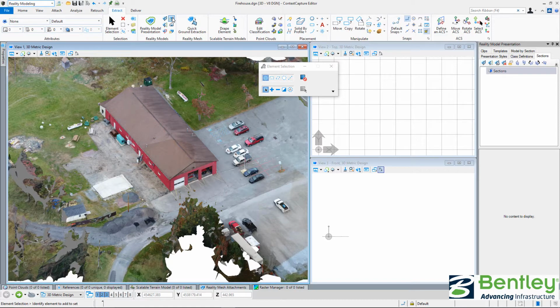So what I'm showing you here, if you have somebody going out and giving you LiDAR, you'll be able to create a surface from that LiDAR too. Many times if you're getting airborne LiDAR, depending on the company giving it to you, it could be classified already. If it's not, then we have the ability to do it right here. Also, some of those are algorithms that were run, and they're not the best programs. They don't do it fully accurate. For example, some street signs and utility poles could come up as vegetation because the software thinks it's a tree. In our case, our main focus is using the bare ground.